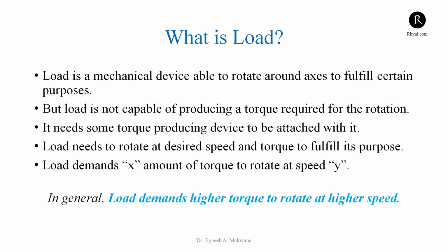However, most loads develop a torque opposite to the supplied torque while it starts rotating, like fan, blower and pump. But some loads are also capable of producing opposite torque at standstill, like lift.